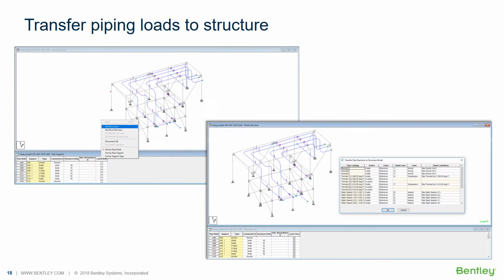for sure before continuing with your combinations and analysis. So again, once you get through that dialog box, on the bottom of the piping tab in STAAD you will again be able to review these connections in here. It will show if it's connected to ground or if it's connected to a node. You will be able to assign a distance along the beam and check on a lever arm.